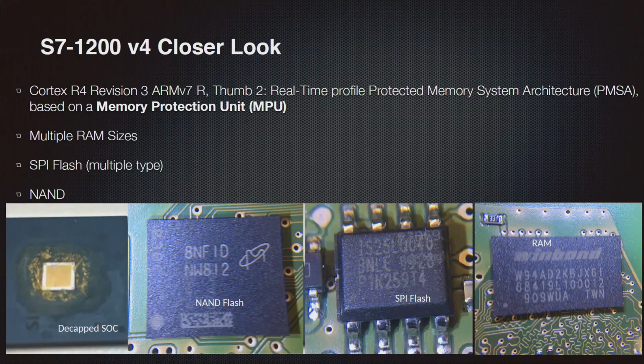Here is a look at not the computation side, but the storage side. We can see the different flashes in a close-up view for the firmware one, the bootloader one, and the RAM chip as well. It notably carries an MPU as well, so there is some possibility to configure memory protections, in order to deal with any memory corruptions that could occur, or maybe also code running inside a data section. You can try to prevent this by using the MPU, which is also used, as we can see in later slides.